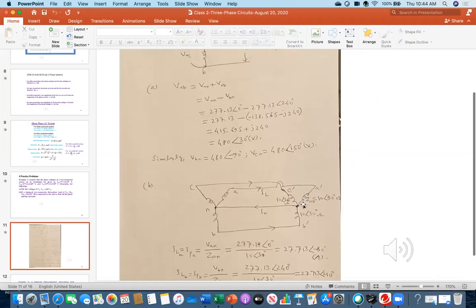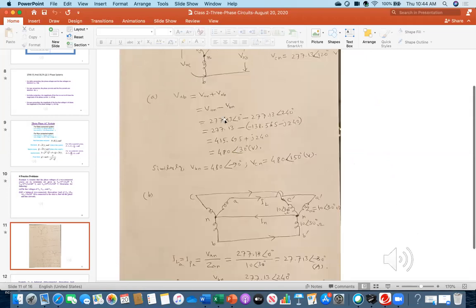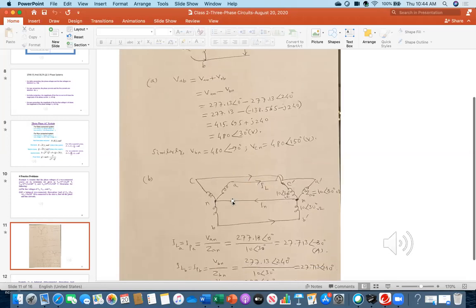Okay. So everybody see, this is the left side that was given, the thing that we dealt with, and then those lines are going and they are connected to a three-phase load. And again, it is Y connected and it has a neutral point. So you could connect both neutrals, because ultimately both neutrals will go to the same safety ground.